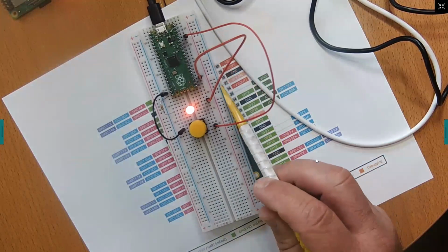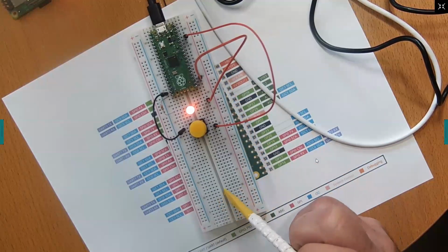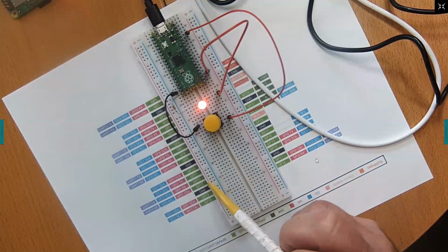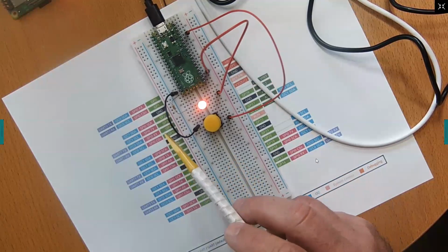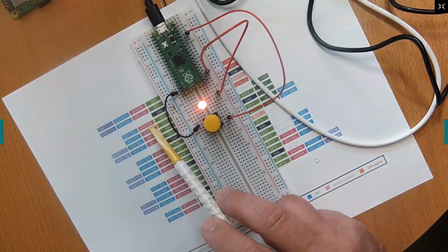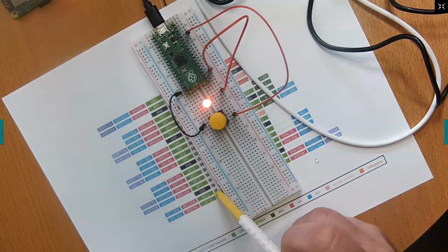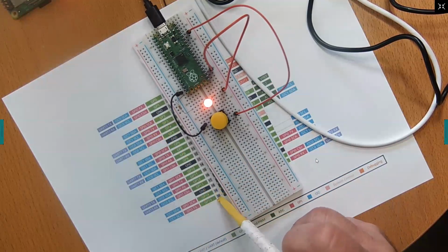And 21 through 40, right? Because there's 40 pins on this thing. But what we're going to address are the green, right? Unless we're doing like I2C or SPI. So on here, when we're addressing it programming wise, we're doing it via the green ones. So 15 is actually pin 20, right? On the Pico, and 14 is actually pin 19.